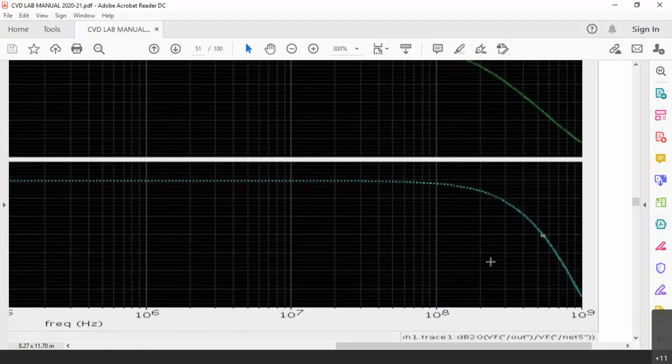Now, you can see that the amplifier is having somewhere around megahertz only. It is not having gigahertz gain. Its gain is going down. It is having a few megahertz of bandwidth only. Why? MOSFETs have a lot of internal parasitic capacitances. It is very difficult to achieve larger bandwidth with MOS amplifiers. It is easy with BJT amplifiers that way.